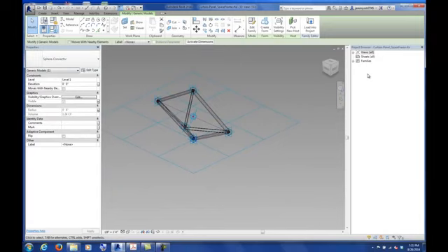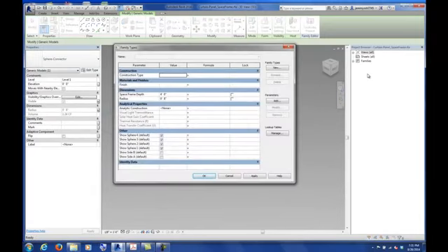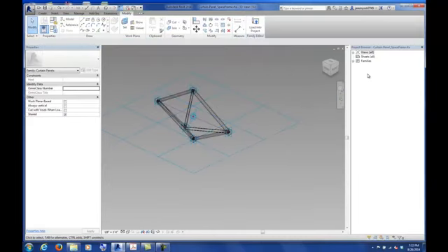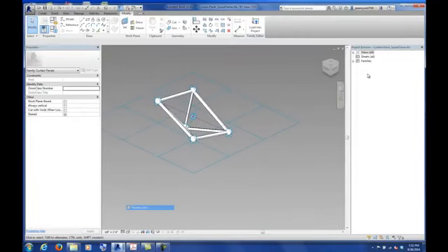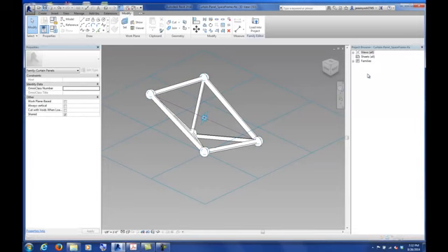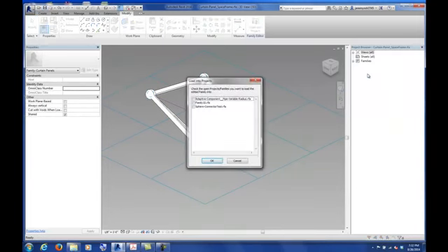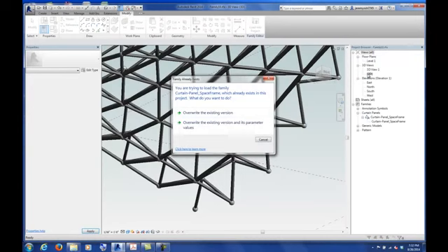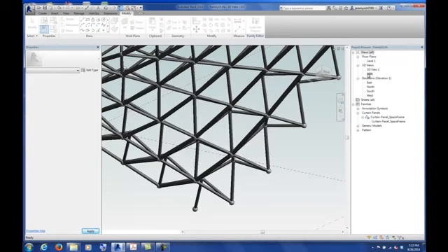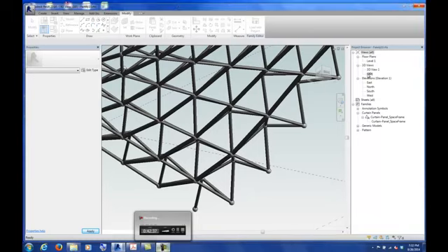And now in my family types dialog box, all I'm going to do is turn off all of them except for sphere 1, so that when it loads into the next project, hit save here, it's only going to show the one corner, which means I'm not going to get identical instances everywhere. But then I'm going to have to eventually go around and do what we did at the end of your assignment, which was to select the ones that were missing the spheres or the pipes and toggle those buttons on and off. And while this is loading, I'll step around one more time and answer questions.